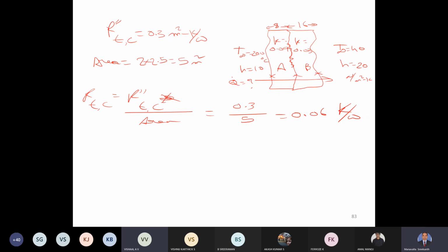So depending on different materials, we will have different thermal resistances. A good conductor will have a low thermal resistance, whereas a bad conductor will have a high thermal resistance. So the drop of temperature to conduct 1 unit of heat energy, or rate of heat, is the resistance. Okay, so this is the resistance of this particular contact.